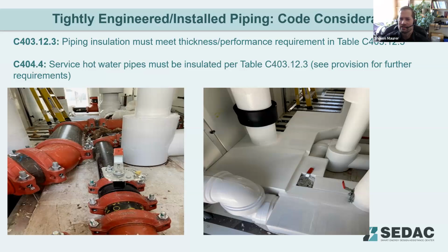And so there has to be some coordination in both architectural design when you're looking at the drawings and things like that, coordinating with the mechanical contractor when they're coming up with their design drawings as well, and then actual installation in the field. In this case, had there not been this supporting pad poured on the floor here, the floor may have been low enough to allow for proper insulation, but then they poured this slab underneath this piping for some support purpose, and now the insulation can't fit. And so this becomes non-compliant for energy code purposes. And now it's a pretty major retrofit to undo that and correct it.